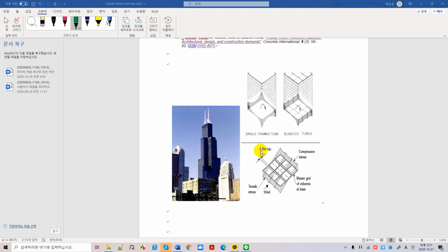So you try 3 meter, 4 meter, 5, 6, 7, whatever, and pick the load from the computer output, from all the columns, and then try to see the distribution on flange frames and web frames. Then you will decide whether you have the column spacing which is close enough to prevent the shear lag phenomenon. All right.